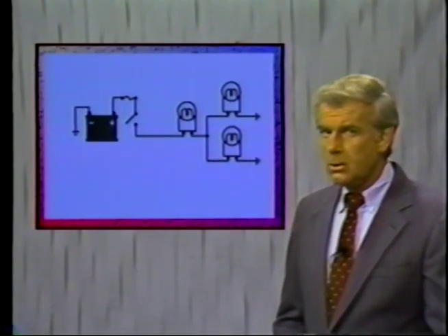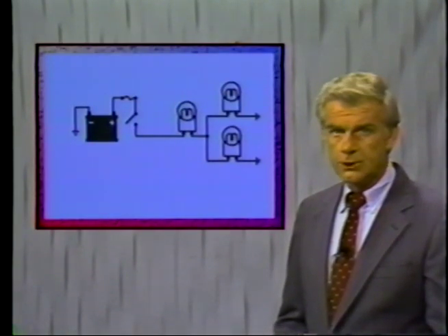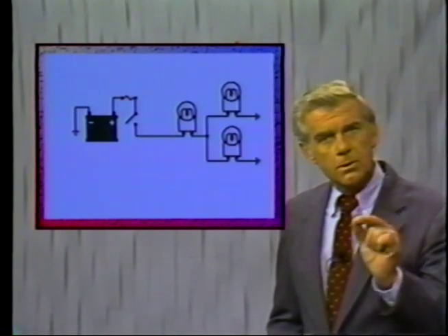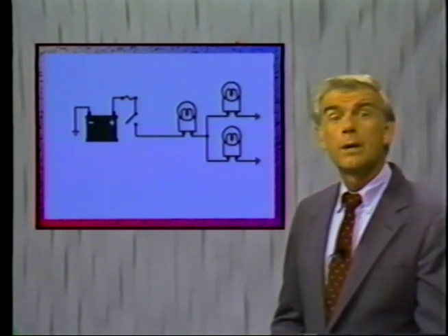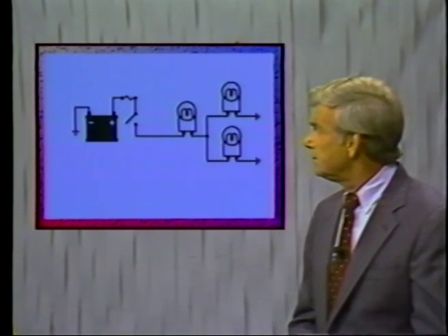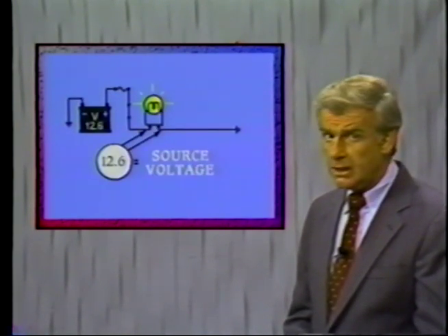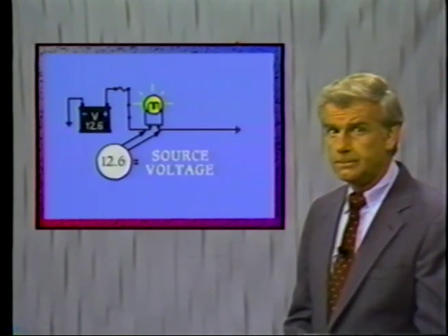To prevent fire or damage to the circuit from overload, a protection device such as a fuse, a fusible link, or a circuit breaker is necessary. As more loads are added to the circuit, they can be wired either in series, parallel, or in a series parallel manner. Knowing how the loads are wired is an important step in troubleshooting because the expected voltages will differ depending upon the type of circuit configuration. Some failure patterns are unique to a particular circuit configuration.